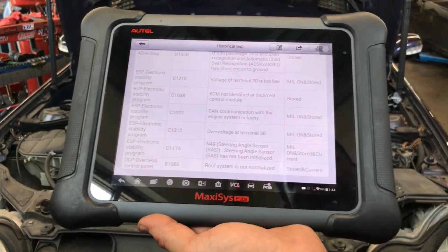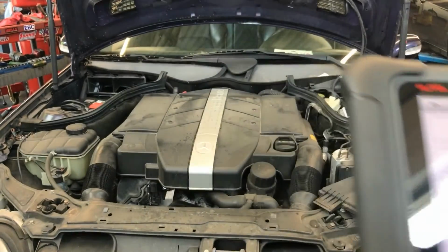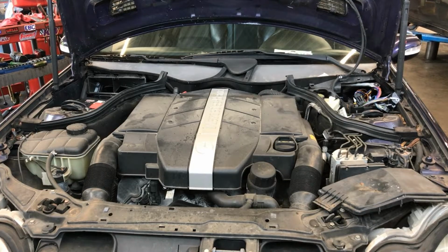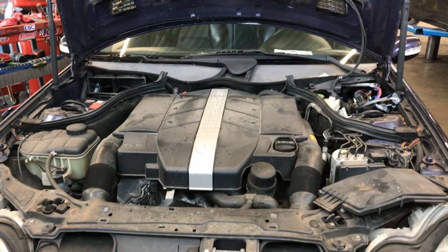So I erased all the codes, and then just on the engine computer, I was starting to get codes like misfires, and still the engine wasn't even running, and then the problem with the no start. I also noticed a current draw around 6 amps. It went down to like 2 amps and then to half an amp, which is still too high. So I took a decision and removed the engine computer.